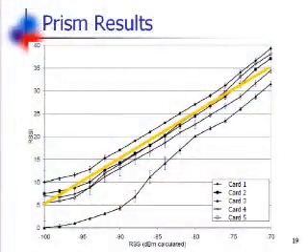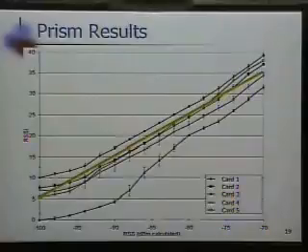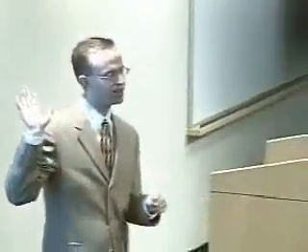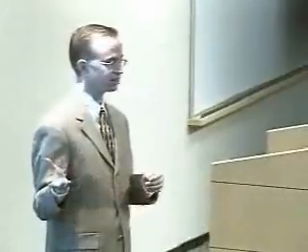And so what we got in reality is shown here for the Prism cards. An idealized result is shown with the gold line. That shows a slope of 1 dB like we'd like. So we see at the start, and for higher RSS values, that we are pretty linear. That looks pretty good. As we get down to the weaker received signal strengths, we see that we lose linearity.